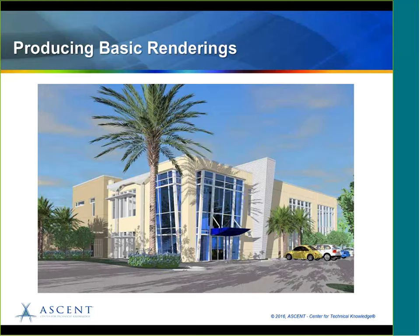The rendering itself will put the shadows in, but as you're trying to get everything set up, you can go ahead and get your shadows. You will need to set your sun settings, especially for an exterior view like this. Also, you can add lights.